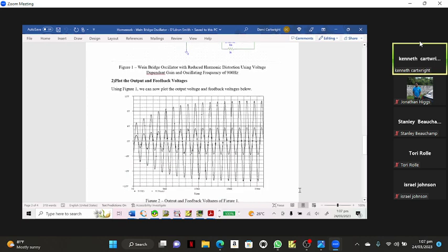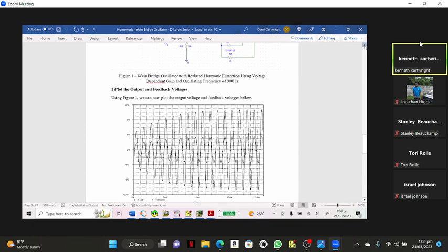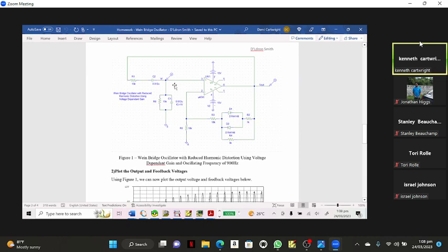So we got two voltages here. The bigger voltage is the output voltage, and the smaller voltage is the input to the op amp, or the output of H of S, and of course that should be roughly a third. Why? Because the gain here is 3, so the output is 3 times the input. So see what happens here.